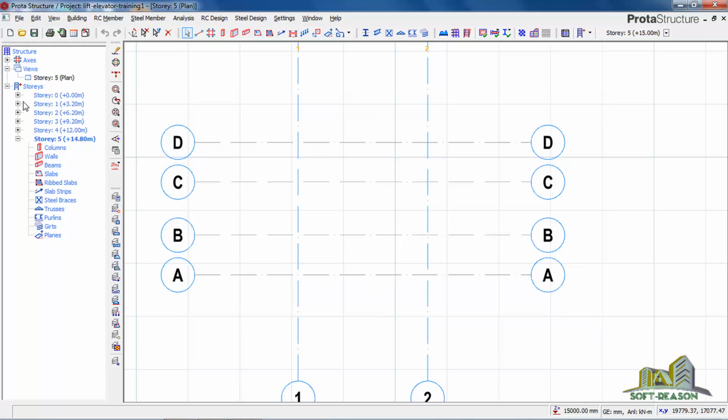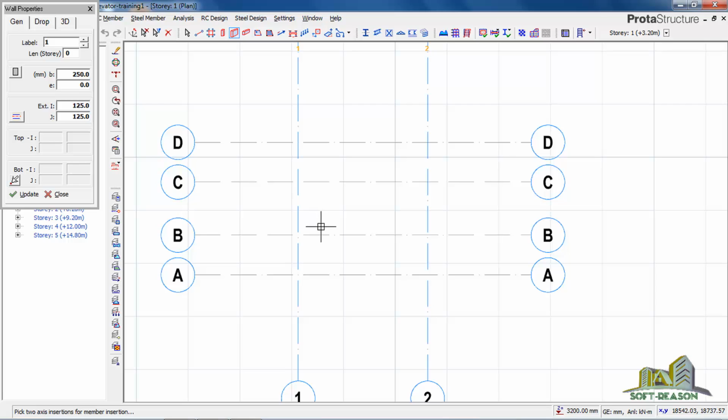All right, so we go to level 1. At level 1, you activate your shear wall. We want to use a shear wall of 225. Then select the center, and change it to 112.5, that is half of 225. Okay, 112.5, and so we will click first point.